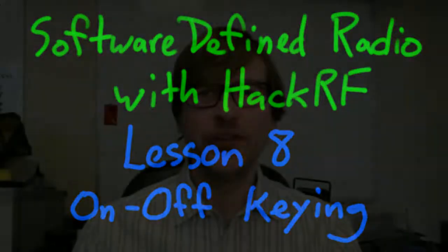In this lesson we will receive and analyze a radio signal from one of the simplest types of digital radio transmitters, a garage door opener remote. The first thing we'll need to know in order to receive the signal from this device is its frequency of operation. There are technical means of determining the frequency, but my favorite method is to use the FCC ID that is printed on the device.